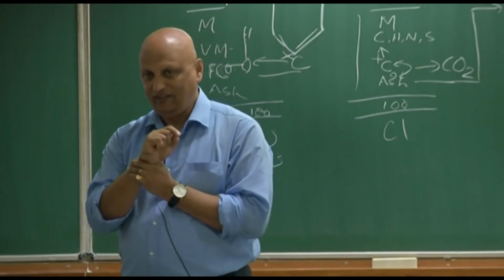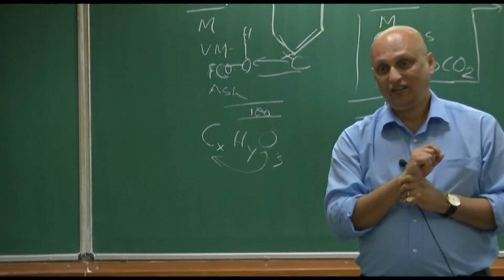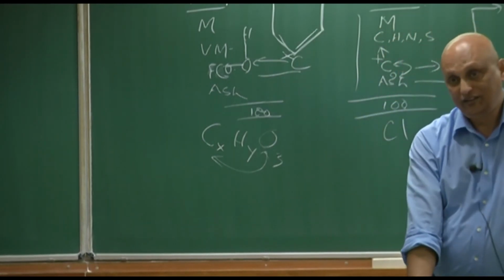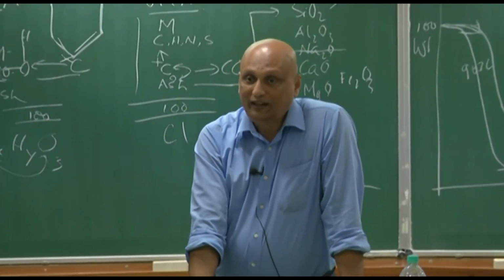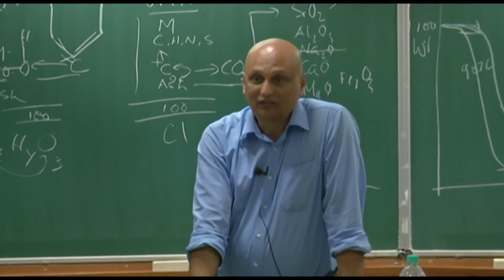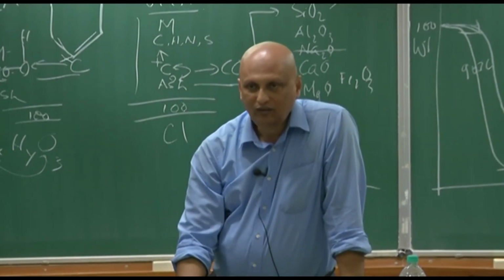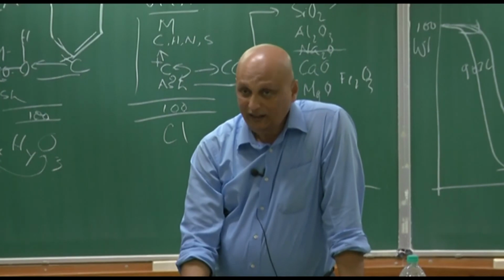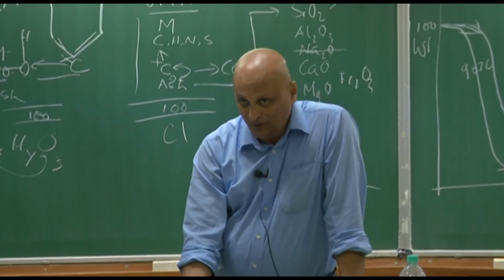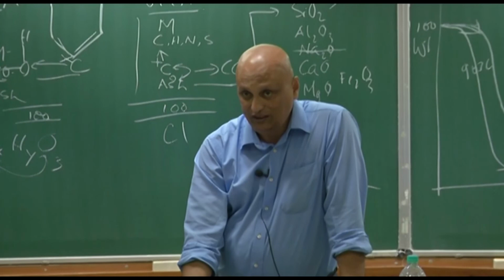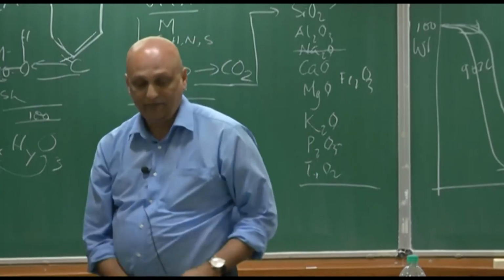But if it is molten well enough, and if its viscosity is low, then it's not a problem, it will flow. If you can predict that the viscosity will be low, then it is even better, because then you will say to your engineers, let it grow, it will flow away. That's the principle with which the entrained flow gasifiers work, that you maintain the viscosity in an entrained flow gasifier between 25 and 150 pascal second, Pa.s.